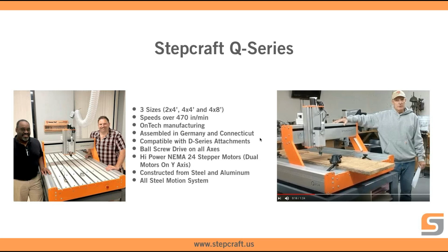because they're meant to be workhorses. Everything's ball screw driven. We're using, I think they're 4 amp NEMA 24 steppers, and we have dual y-axis stepper motors on the y-axis on the 404 and the 408 machines. So the 2 bigger machines have dual Y motors. Everything is constructed from steel and aluminum.